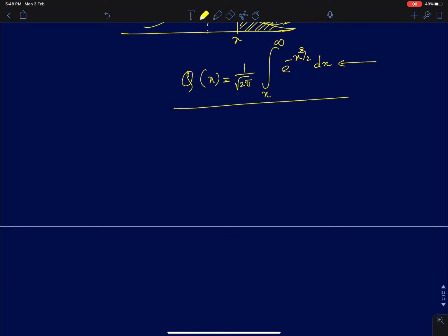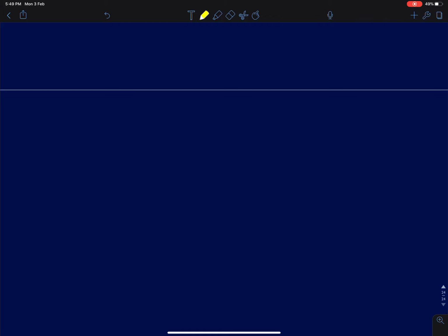Now, keeping this in mind, we will go back to this problem of signal detection. I said we had a receiver wherein we take your orthonormal basis function and correlate it with your received signal in the presence of noise, and then we compute the integral from 0 to T of the product. That's what I call correlation.